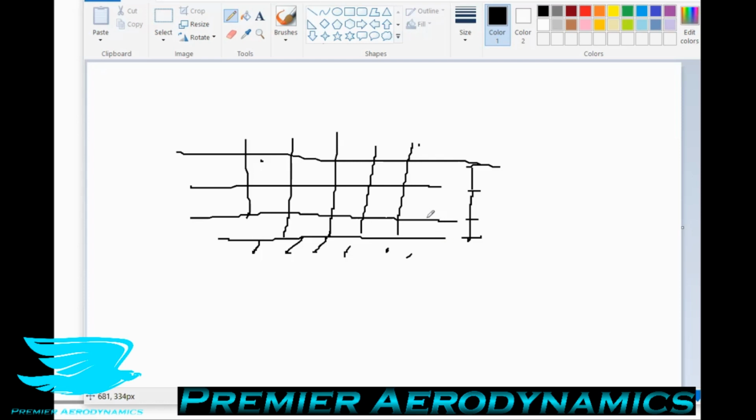We then use those equations on poorer quality CFD to be able to use a thicker first cell height, which means we can reduce the number of cells and still get a good result, hopefully. Now, there is a limit to this: if the first cell height is too thick, then these equations start to break down because you start to get complicated flows that are very particular to what we're looking at.